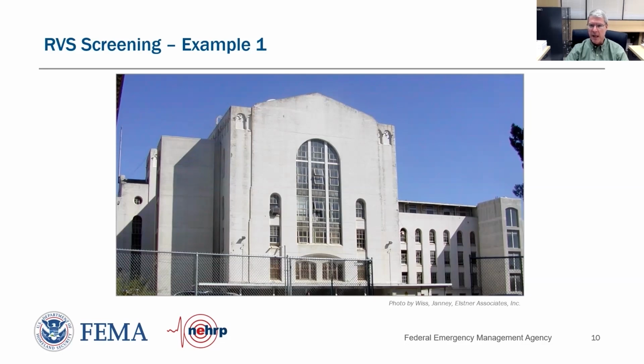Does this look frame-like? There is some regularity on that back portion that's inset a little bit with the smaller windows, but I don't see any joints in the concrete. It looks pretty continuous. Right, so no real frame action. So if we get rid of that, what about C1, which is moment frame? That looks like too much concrete on the face of the building to be acting as a moment frame.